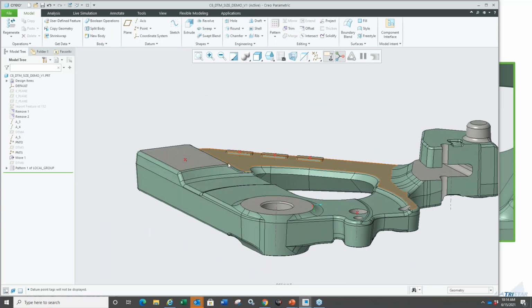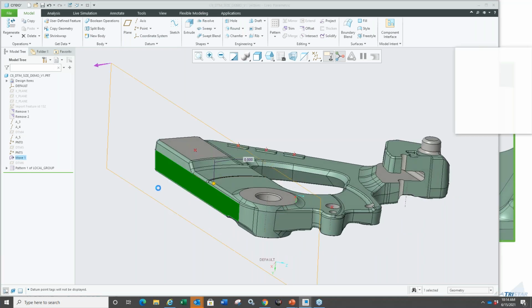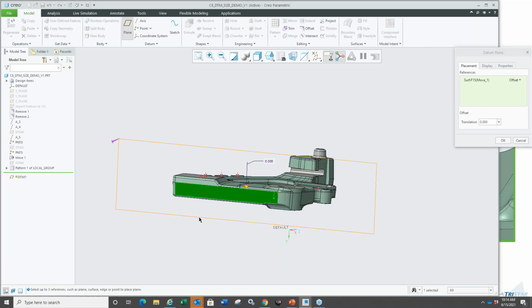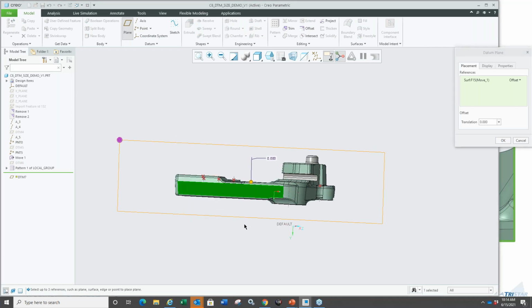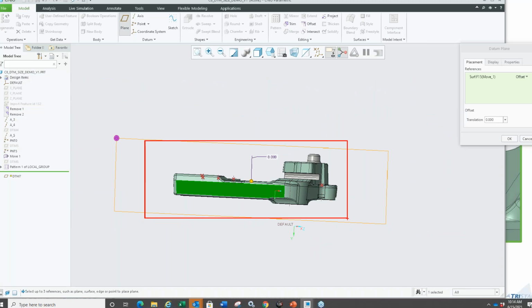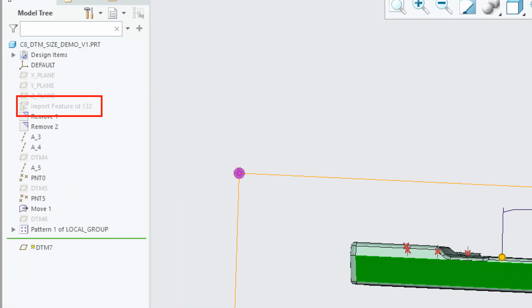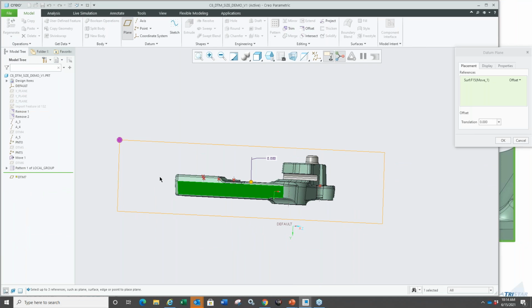And also when you create new planes, for example, let's say here I want to create a new datum plane. As always, by default, it still is like in Creo 7 and prior, where it will fill to the model outline. So in this case, why is it going a little bit farther? I do have an import feature, as you can see, and the import feature may have some surfaces or edges or curves that it's probably using, and it's probably hidden, and that's why you can see that it is essentially a little bit larger than I would have liked.